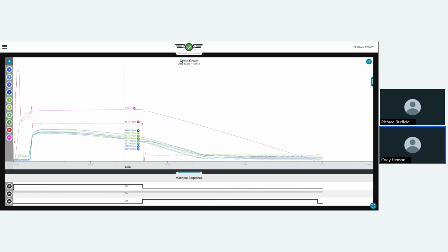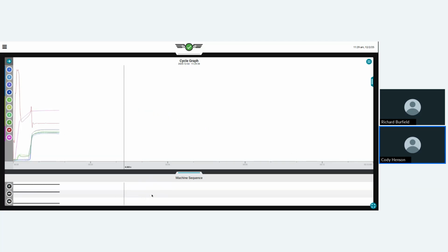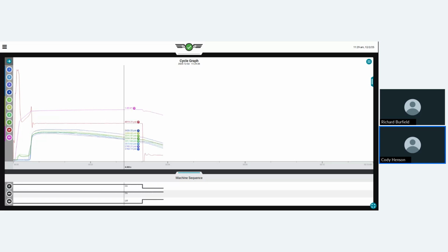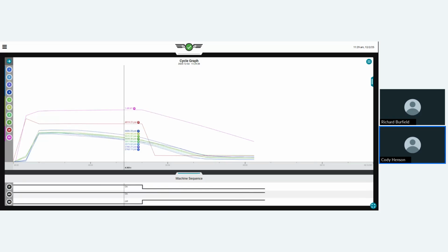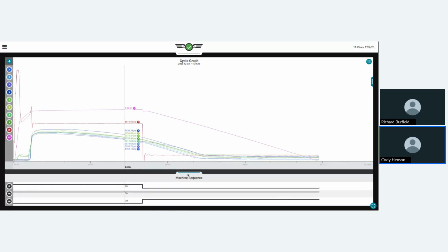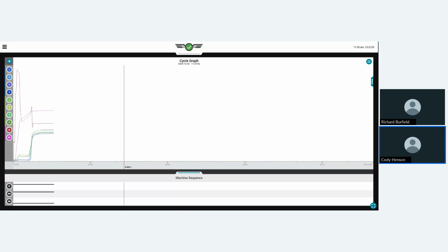Below injection forward, we have a mold closed, and then there's a screw feed. And just another tab, you may not have it up often, but if something is not happening the way that we think it should be, it is a useful tab to look at to make sure things are firing appropriately and when we would expect them to be.